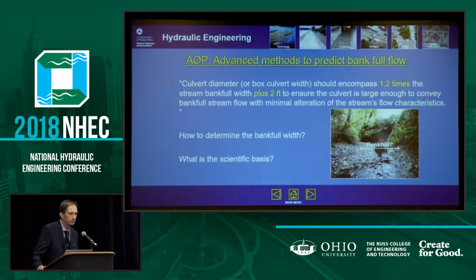We heard maybe to use the Q2 or Q1, or just go out into the stream and measure, and then add 1.2 times the Bankfull width, and maybe add some 2 feet or something. But what we try to do is to get a better understanding of what that is, and maybe use a more scientific basis for that idea.